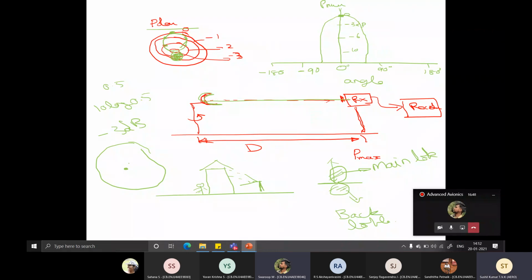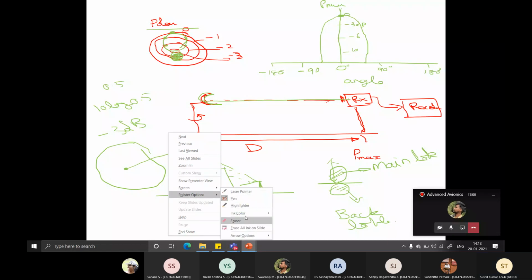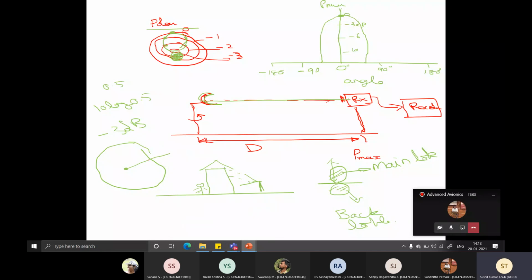Yeah, so what's going to happen is, let us say the antenna is pointing at 45 degrees, okay, and we have an aircraft which is approaching in this direction, 45 degrees northeast, okay, it's coming from this direction, you'll see a blip, okay. The same thing, if there is a back lobe and an aircraft is approaching from southwest, he is coming actually from this direction, but it will be seen as another blip coming in the northeast direction, isn't it? So you are actually confusing the radar now.